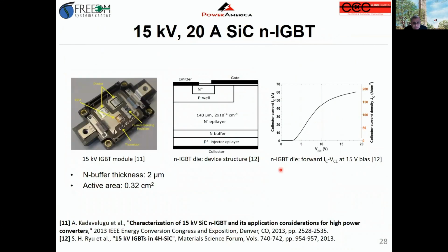Now, a little bit of the comparison with the IGBT versus the 10 kV MOSFET that I've been talking about. With the 15 kV IGBT, the motivation to go there would be higher current density with a smaller die. You can see that this die is 8.1 millimeter by 8.1 millimeter. This is a 20 amp die at 15 kV. There are two JBS diodes connected in series because they're blocking 8 to 10 kV for this co-pack.